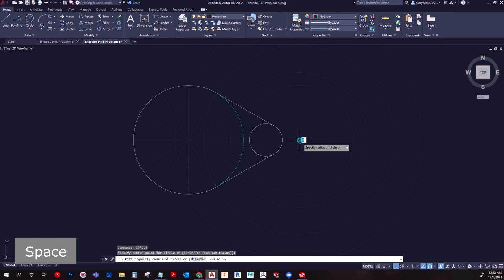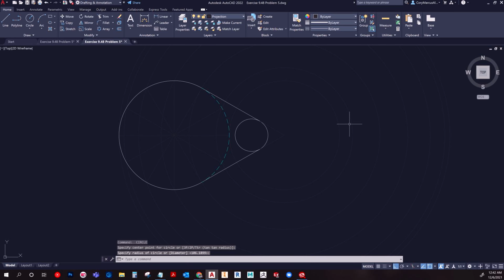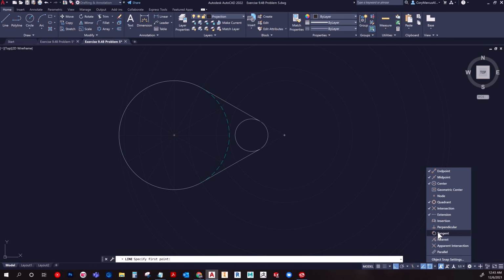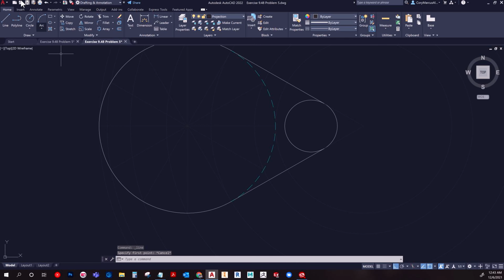So I'm just quickly going through, and I do have intersection turned off so that there is no issue with any kind of erroneous snap. When you have so many parts like this, or lines like this, where possible, you should absolutely avoid using intersection as a snap option. If you have it on, it's just going to cause problems. I've actually been lucky, apparently. It did not cause any issues, and that's a rarity.